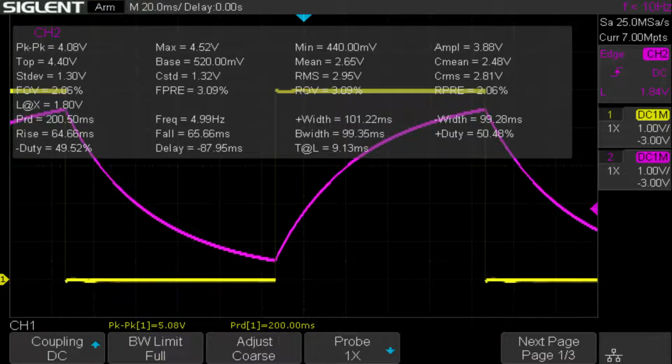You also have another part of the lumped circuit model, such as transmission lines, that takes care of characteristic impedance and time delay. So those are the four main lumped circuit model elements where you can pretty much classify or organize any behavior that's happening in electronics to one of these circuits.